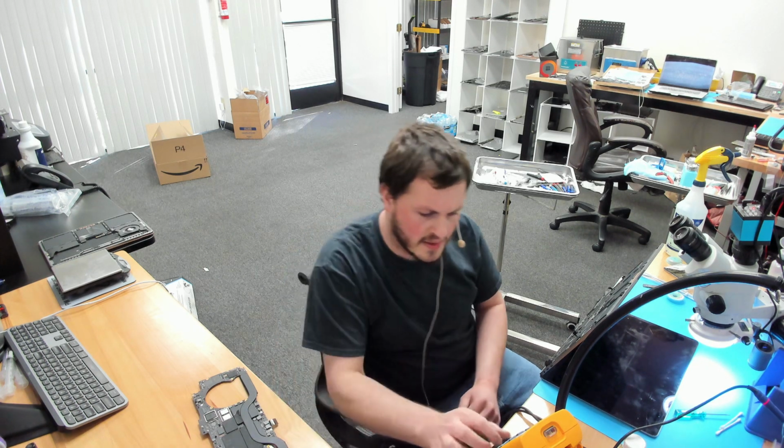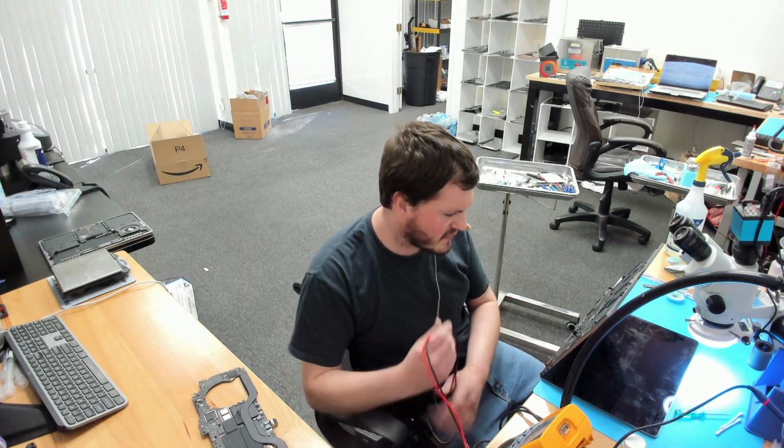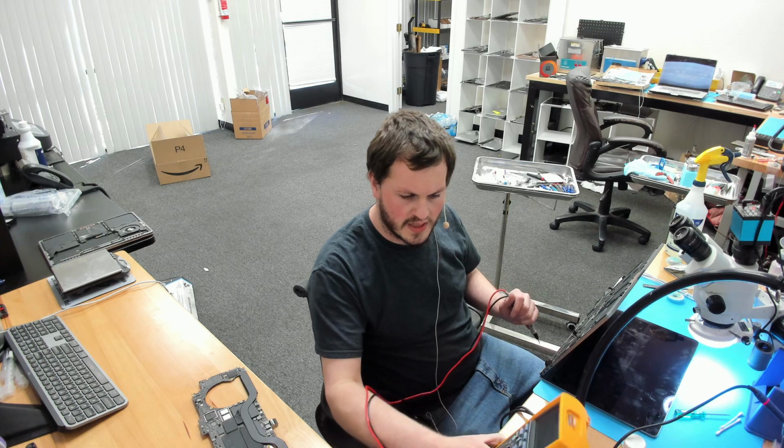So we're going to go ahead and open back up our board view and try and figure out what might have happened here. So first off, I want to see if we're getting any voltage on 2V5 NAND now on this side. So we could easily measure that. We are charging the battery. That is different than before. Was not doing that in the past.